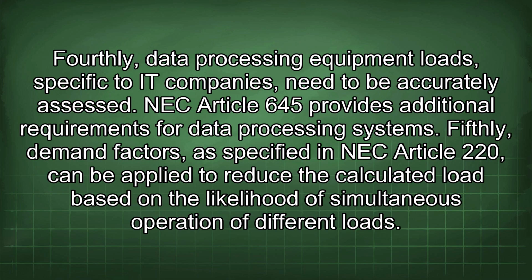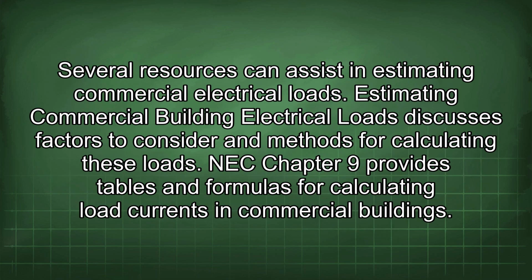Fifthly, demand factors, as specified in NEC Article 220, can be applied to reduce the calculated load based on the likelihood of simultaneous operation of different loads. Several resources can assist in estimating commercial electrical loads. Estimating commercial building electrical loads discusses factors to consider and methods for calculating these loads. NEC Chapter 9 provides tables and formulas for calculating load currents in commercial buildings.